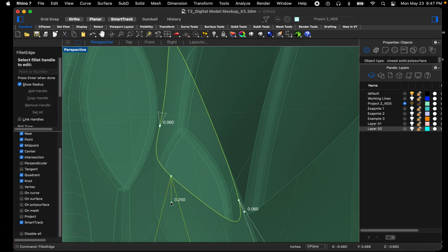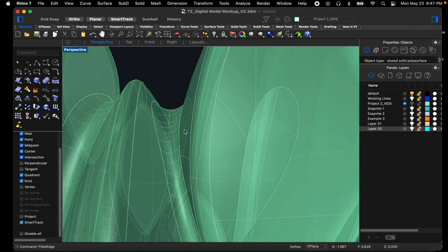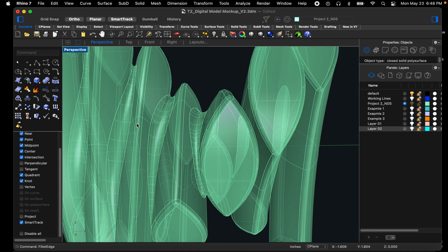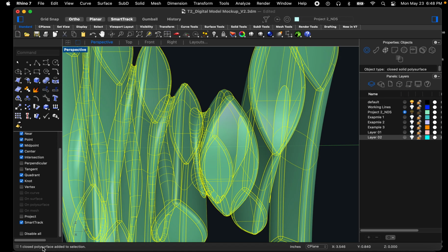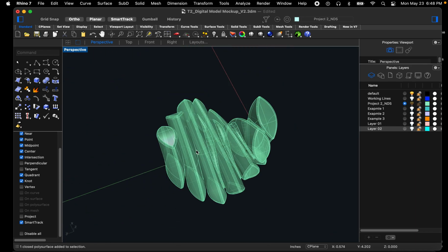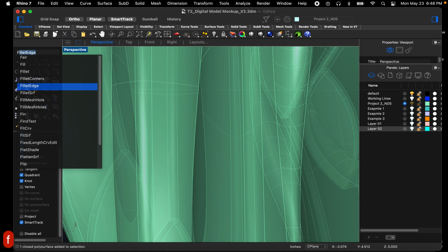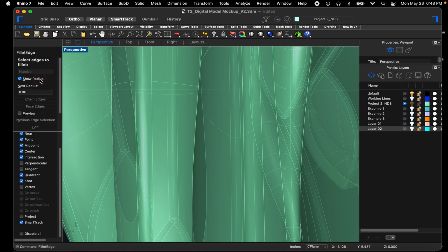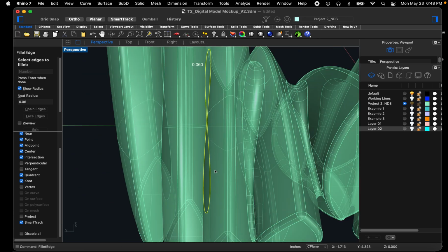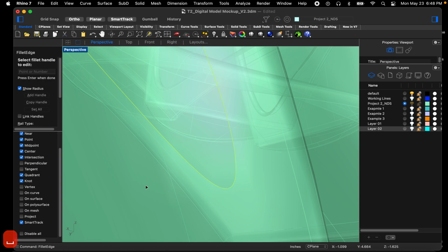As long as it's close, it's good enough for what we're doing currently. And more importantly, that it still maintains our watertight condition. Right? So when I do this, I select one closed poly surface added. Perfect. Now, if that changed from closed to open, then there would be cause for concern. So then go back and dive in to figure out why we went from closed to open, and that's part of the detective process.